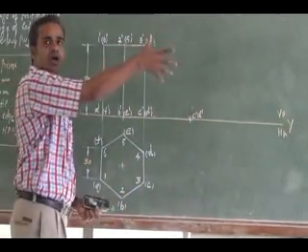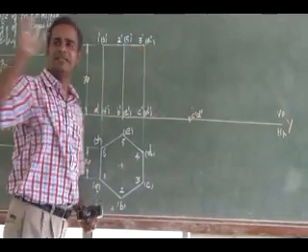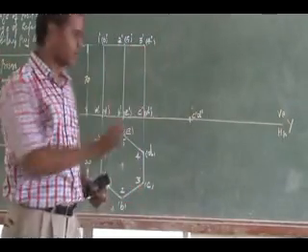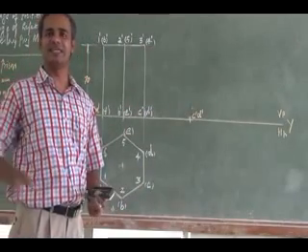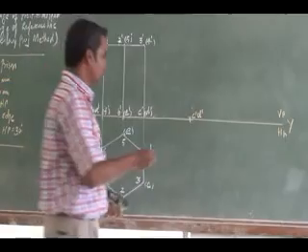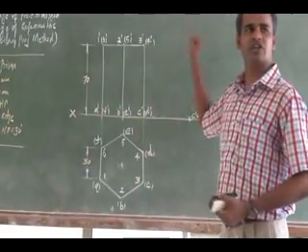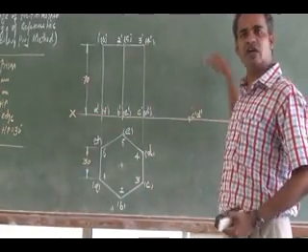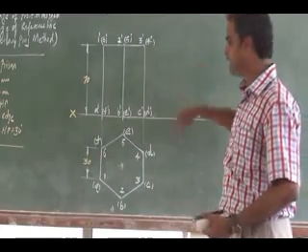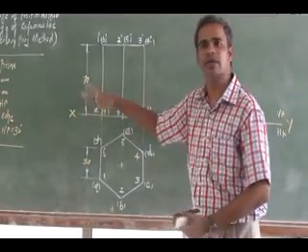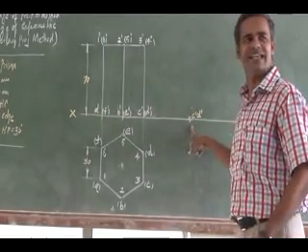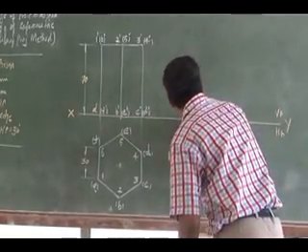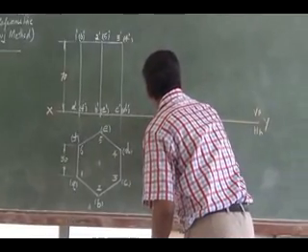Just what I'm doing here, I'm reproducing the front view in a tilted manner. I'm redrawing the front view in a tilted 30 degree orientation. Okay. So for this, the axis inclination I know 30 degree. I'm converting it to the base inclination. If the axis is 30 degree inclined, the base will be 60 degree inclined. So I have marked the resting edge. So just you draw a 60 degree line.